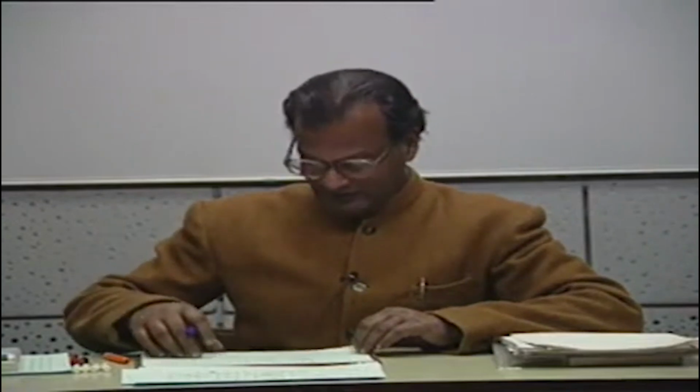more than one sinusoid, alright, more than one sinusoid. That is, if we had another sinusoid of the same frequency or a harmonic frequency, then I could add other terms, V2 squared, V3 squared, and so on and so forth, alright. So the root mean squared value of a mixture can be very easily found out, with the restriction that the frequencies must be multiples of each other or the same.